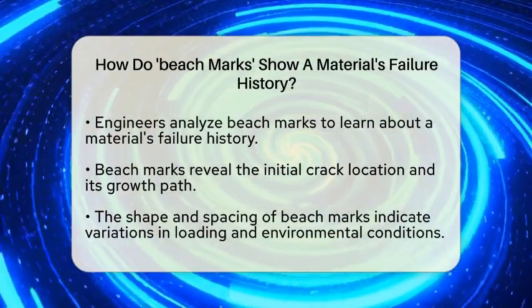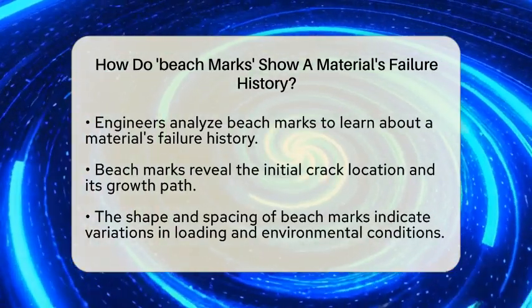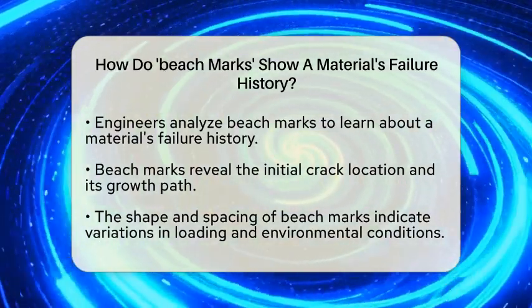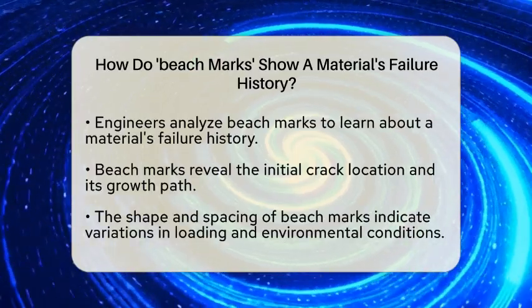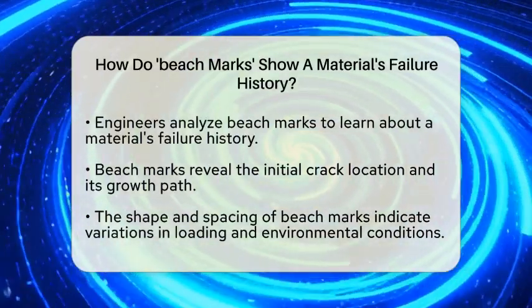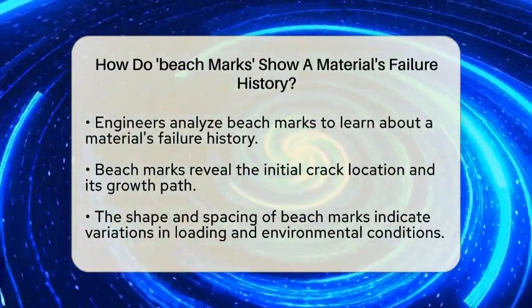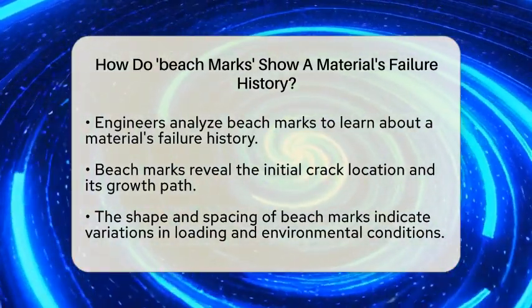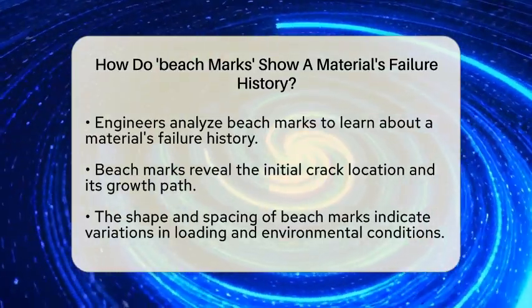Additionally, beach marks can indicate changes in the rate of crack growth. If a crack grows faster or slower due to different stress levels, this will be reflected in the pattern of the beach marks. By studying these patterns, failure analysts can determine the direction in which the crack was propagating and how the part was loaded throughout its life.